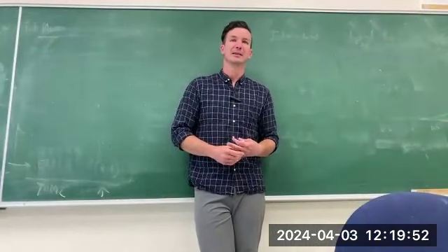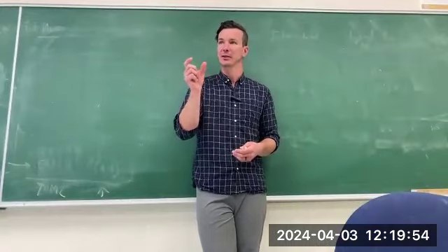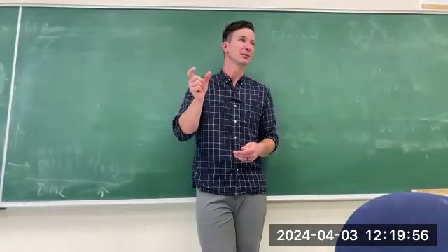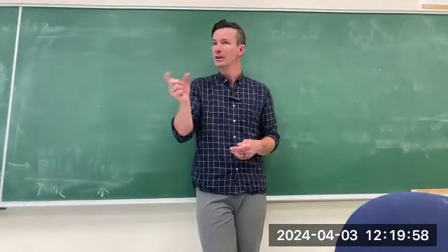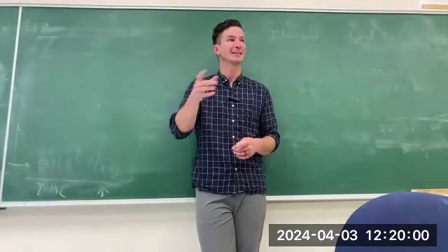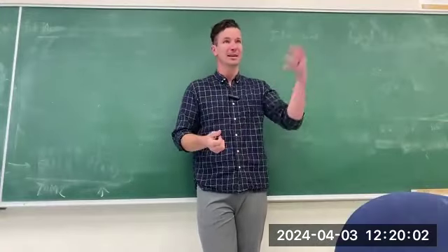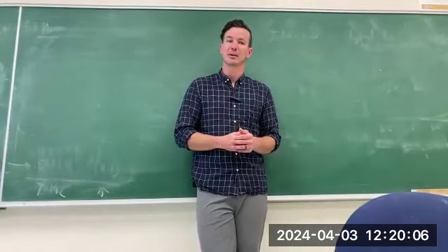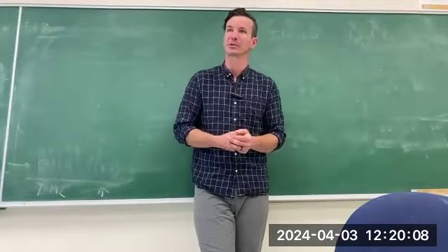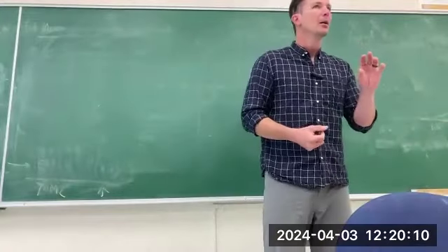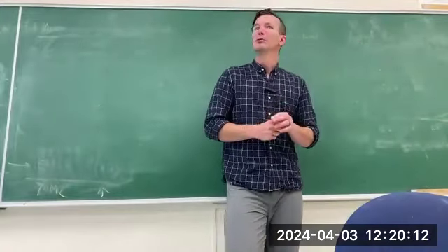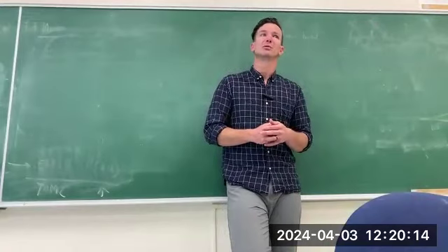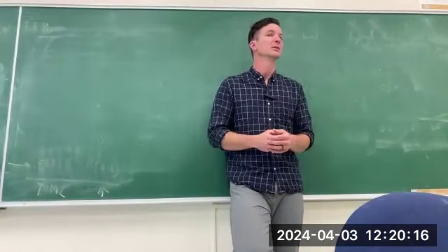Yeah, the thermostat. The stat in thermostat is a regulation. It's trying to keep the temperature constant, and it's doing that by sensing the temperature of the room and either adding heat or taking away heat as necessary. That is what we call a regulator control system, trying to regulate the temperature in a room subject to disturbances.